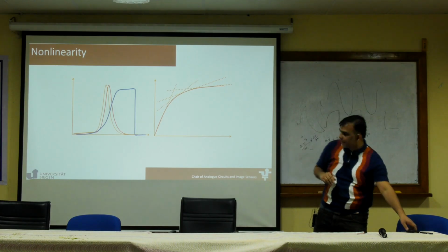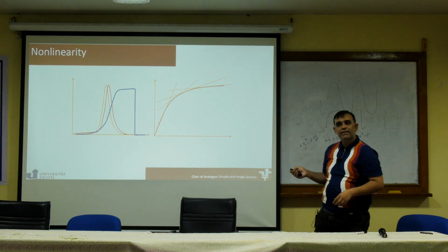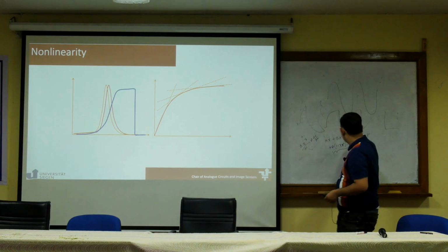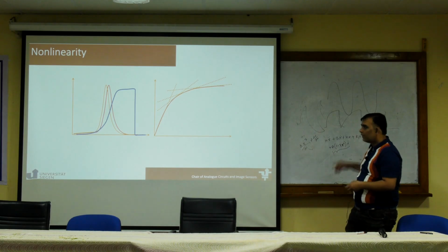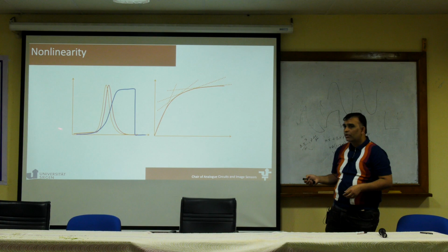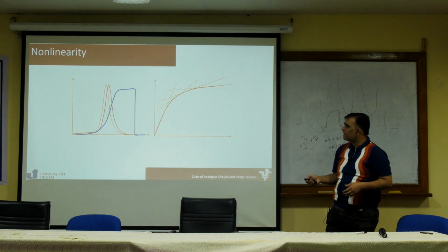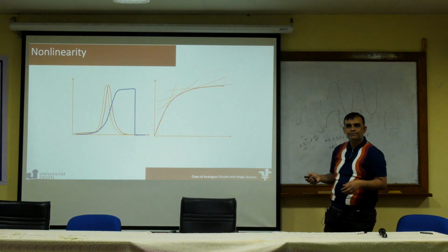I mean, think of it this way. That is the response of a Duffing resonator. If I put kx cubed, what happens is, in a linear resonator, we go up and we go down in the same way near the resonance frequency. A Duffing resonator goes up, saturates, and then has a rapid fall.